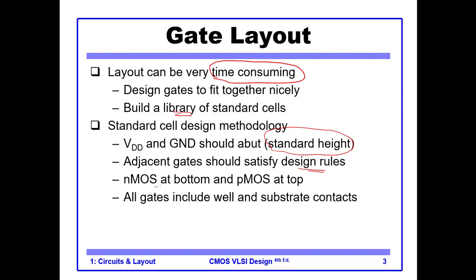And then we say that NMOS should be at the bottom and PMOS should be at the top. So your NMOS are at the bottom near your ground, and your PMOS are at the top near your VCC. Then all the gates must include well and substrate contacts.